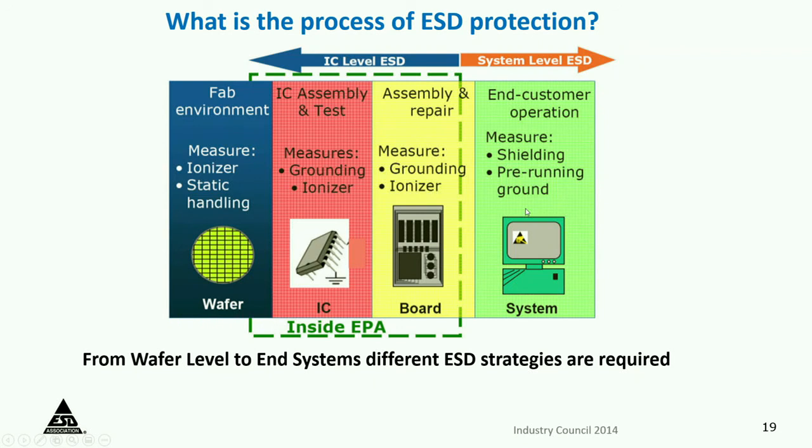Usually when people look at the back of their laptop, you can see a shield that is there to stop you from touching those pins. Okay, it's a grounded shield that is put in there. So this area inside is called ESD protected areas, EPA. So we take care of the devices here. Once they come out, then it's a different strategy for those devices, okay?